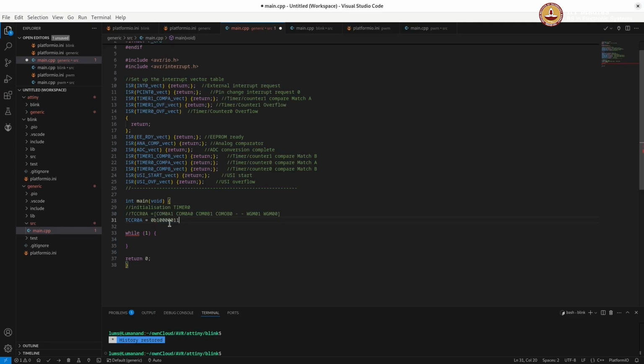So this would be the control word that you want to set. But one thing is that binary not all compilers recognize. So you may have a problem with some compilers. Hex and decimal, of course, the compilers take in. So you can give this. And if you are having the datasheet by the side, this is a very compact way of defining the control word. But the recommended way